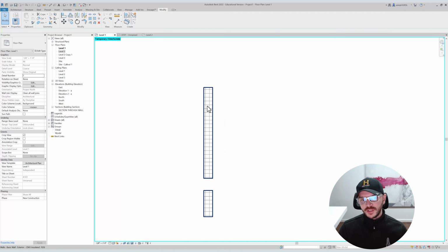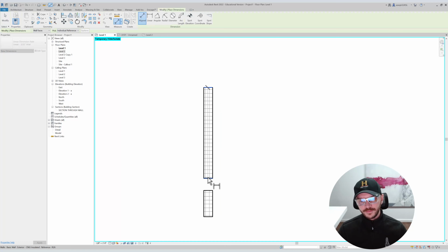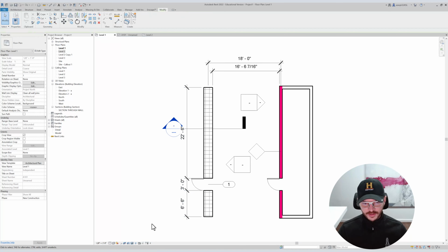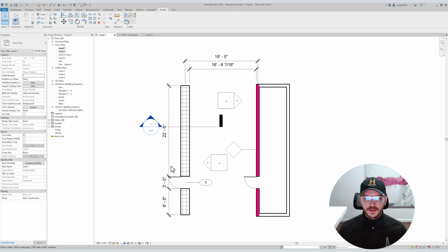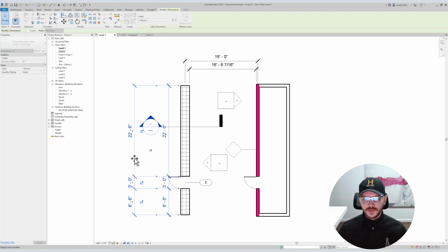Let's say you have a wall here, a window, multiple lines, a lot of notes pointing over here, but you've lost a dimension and it's just getting cluttered. So now you can isolate this, hit DI for dimension, and then you have this guy. You can hit HR to release the isolation, or just go here, and then you can get back to the normal view. Right? And that will be a lot easier on your life once you have a very busy drawing and you need to move faster, right?